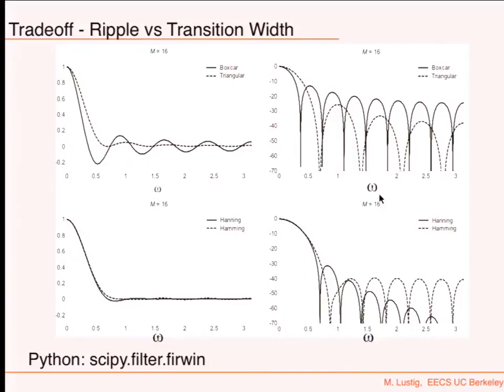So, for a filter, between the taps, what is the length between the taps? Oh, taps, I mean just basically the number of elements. Okay, so we're going to take a window, like an M equal 15, we'll have 16 taps, because it's always M plus 1 that we're going to be using.